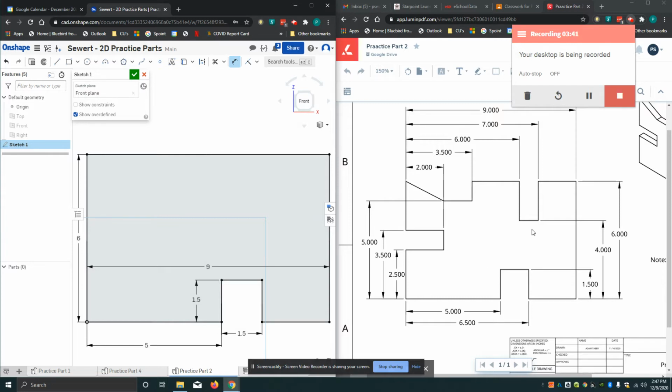All right, now up here on the right-hand side of this one, I've got another rectangle. So I'll start my rectangle tool, and I'll just put it someplace near where I think it's supposed to go. And I can do a little math here. It's 7 inches minus 6. That means the distance from here to here is 1 inch. So I'll change that. Oh, shucks. Well, I'll have to start my dimension tool. That's not a big deal.